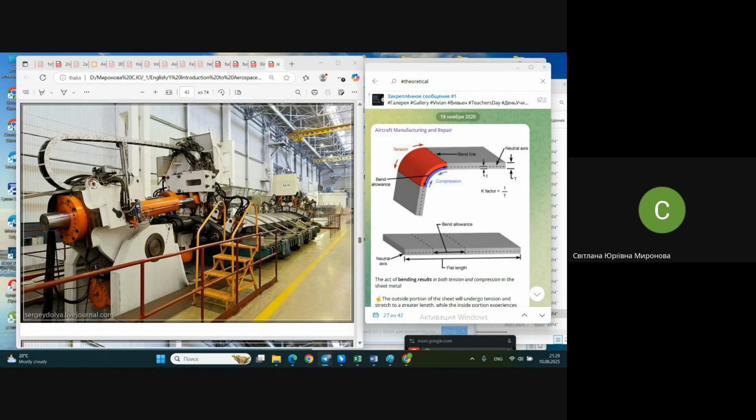It's a very specific machine called a stretch forming machine. They may be, as I said, of three different types, but practically it's a hydraulic press. What you see are hydro cylinders which operate these fingers, clamps. In some types of machines, these clamps just stay in place and hold the part.